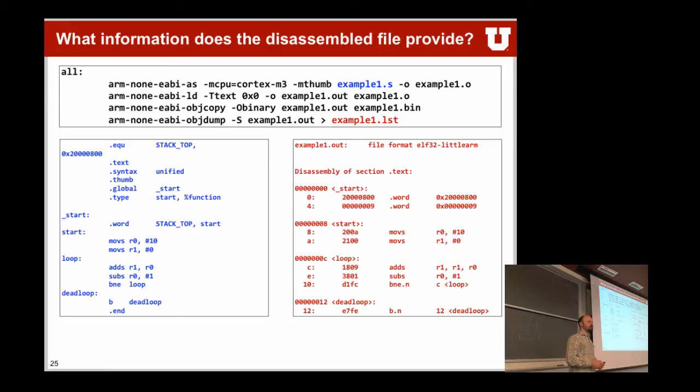And we will see when this is added, the +1, and when it's not. Sometimes you don't have to do it because some of the jump functions can switch your execution mode, but others you have to add +1 to the memory location, or else you will get a hard fault. Sometimes very confusing to figure out what's going on. All right.